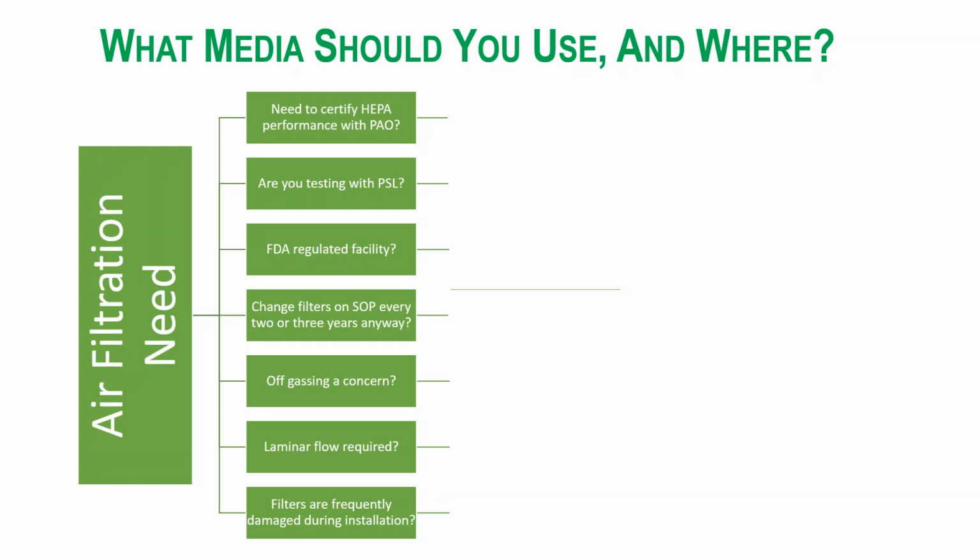It could be quite substantial. So air filtration need, what media do you use and where? If we need to certify the HEPA performance with PAO, I would recommend you go with microglass. Why? Because it has been used with PAO testing for years. There's no clogging, there's no issues.